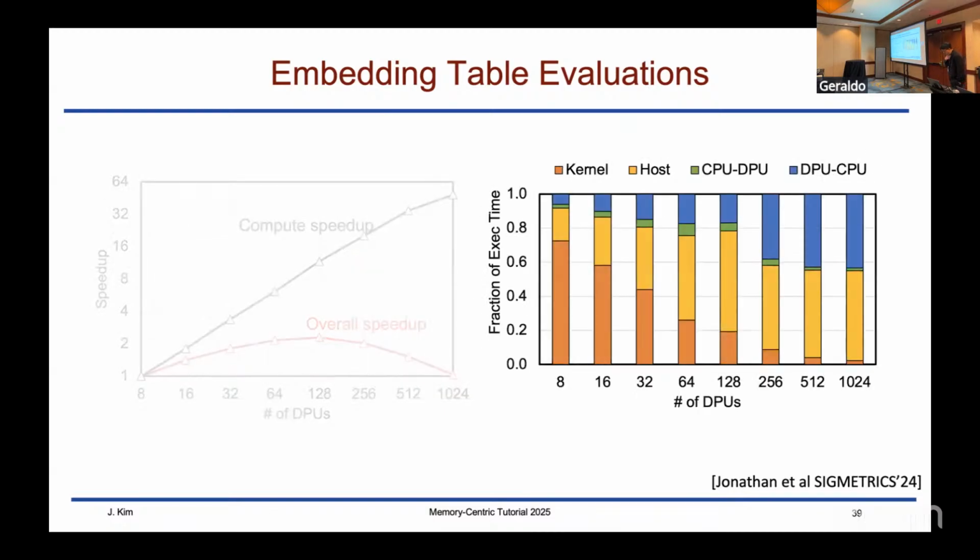The problem here is that you have to do a final reduction for this particular kernel, and a lot of that time is actually spent on the host. If you look at a publication that appeared in last year's ISCA, they look at how you can optimize the host side, and that can significantly reduce the host overhead. But I would argue that that's still inefficient because you still have to go to the host and you still have to come back. So you effectively have a 2x bandwidth usage. And the question is, can we do better?